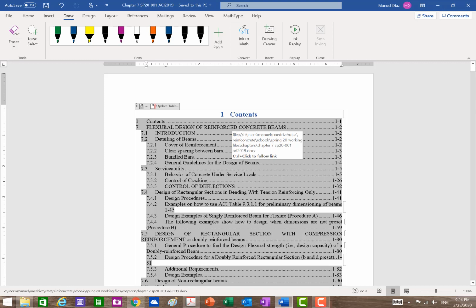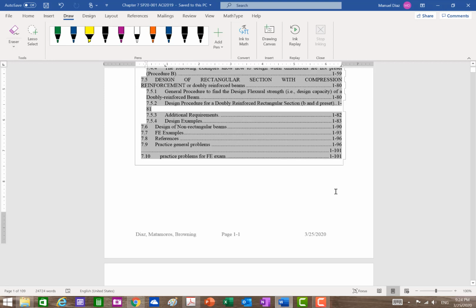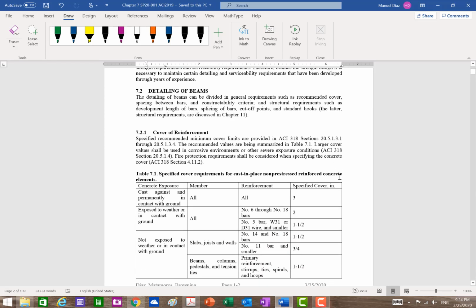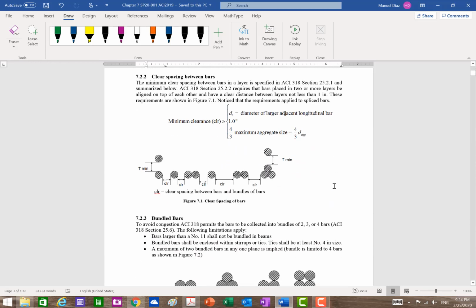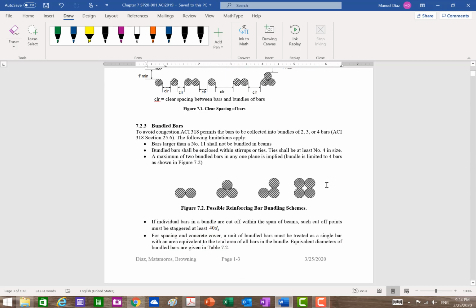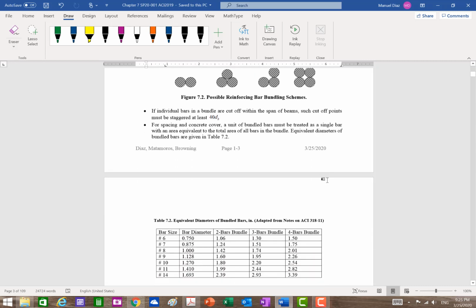We went through serviceability, and in there, the main thing that you learned was your cracking moment, right? We went through cracking moment, and I explained what cracking moment was, and that led us to the definition of your f_r, which is your modulus of rupture. Okay? Modulus of rupture. The modulus of rupture is an indirect measure of the flexural tension capacity of the concrete.